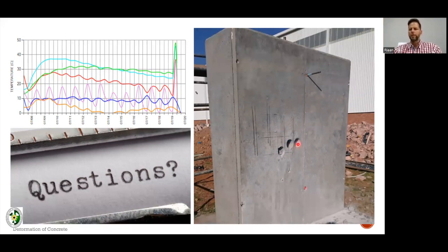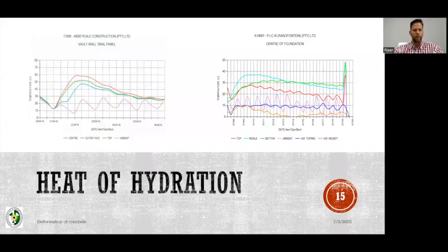That core tested 86 MPa at 7 days. Now, 86, you know, in a week, that's a lot of this red line over here. A lot of heat that you need to get rid of or to manage. So that becomes very interesting.